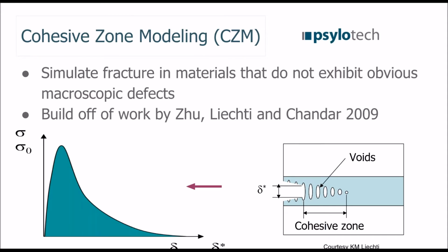In the cohesive zone models, if you're not familiar, we're obviously measuring the stress, the load of the specimen, but then also this displacement here, the crack tip propagation, and we measure the gap here as the crack tip moves. There's a few different ways to measure this, and we'll go over those in the next few slides.